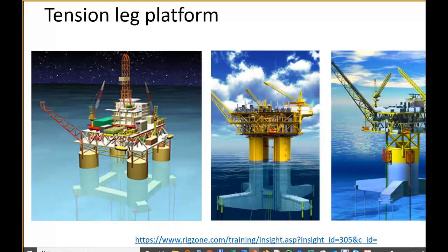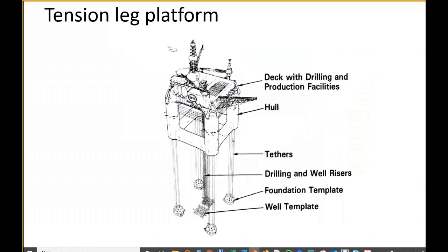Tension leg platform, also another concept. It looks a bit like a semi-sub, okay, but the thing is that, as I told you, it has these tethers that are holding it down. So if I remove these cables, if I remove these tendons, the structure will simply float up. Okay. Looks a bit like that. This also has very low movement, okay, because it's anchored such that it doesn't have too much heave, which is movement up and down, but it has some horizontal movement, sorry.